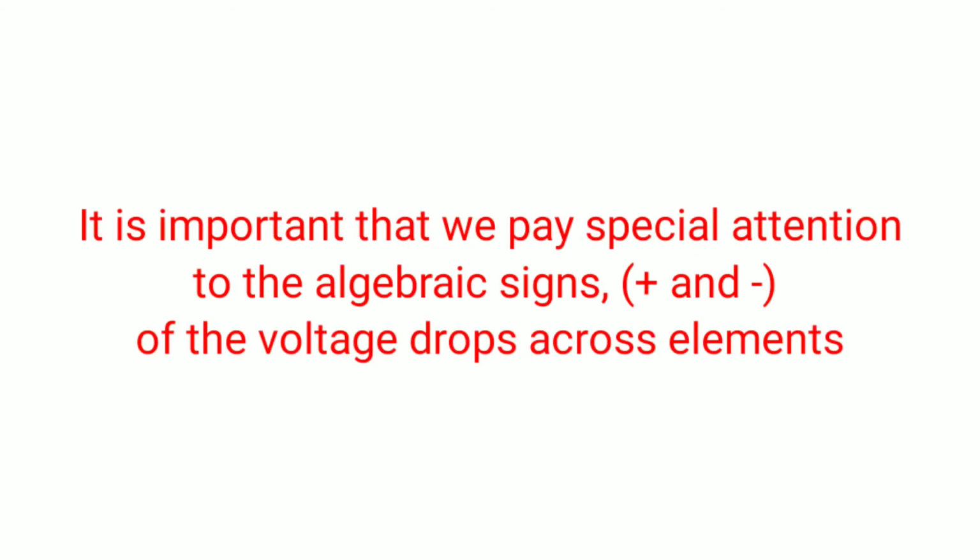So when applying Kirchhoff's voltage law to a specific circuit element, it is important that we pay special attention to the algebraic signs, meaning positive and negative sign of the voltage drops across elements and the EMF of sources, otherwise our calculation may be wrong.